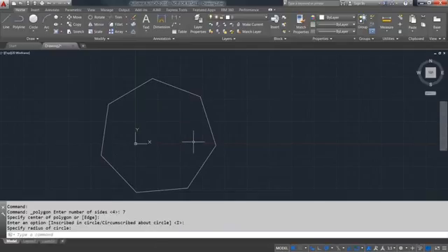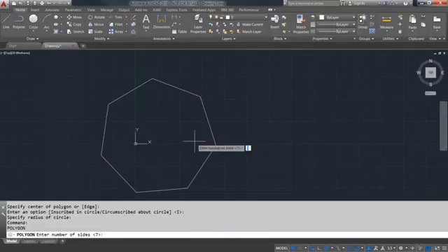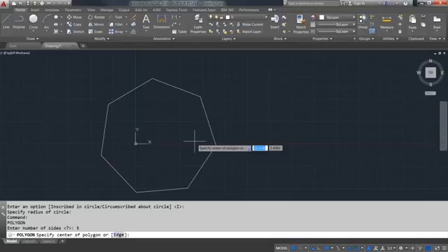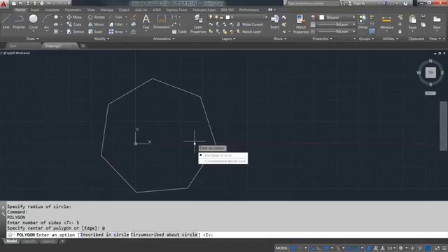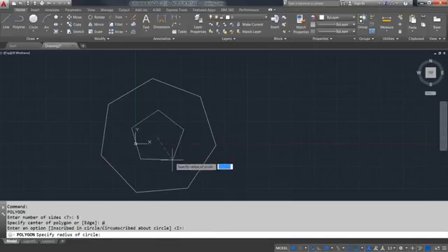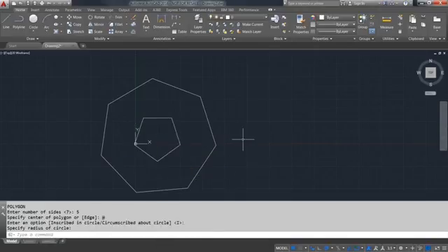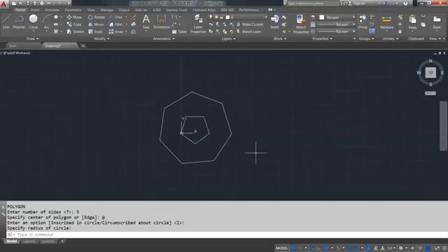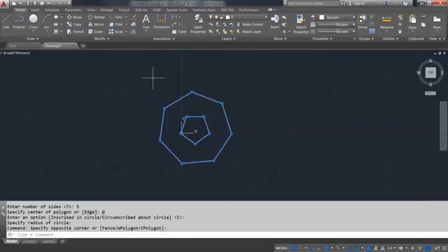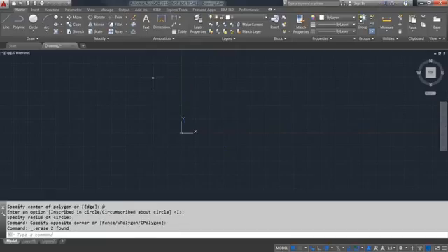And just like with the circle that starts with a center point, the polygon starts with a center point as well. So let's do another one with 5 sides, and for our start point, do the @ symbol, which will start us at the same point as we did the last one. As with all these commands, there's a lot more to explore, so please do so. There's a lot of nifty things in there that you'll find that you probably use and put in your own personal toolkit.